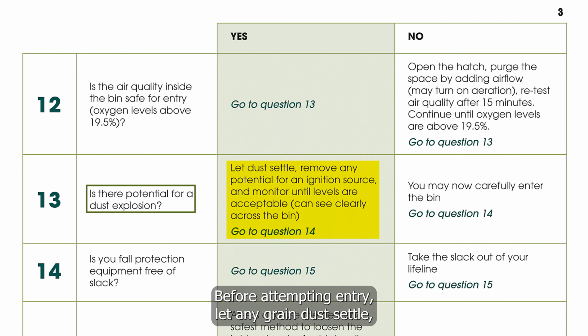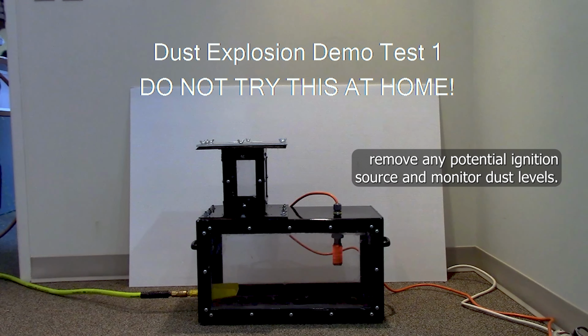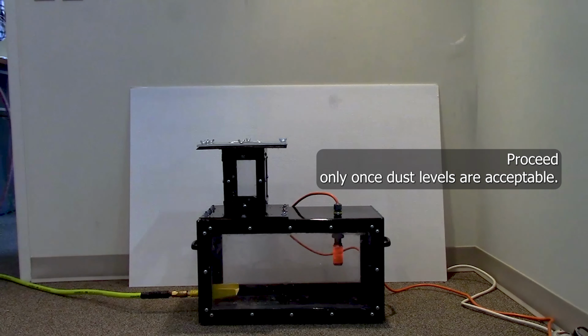Grain dust is highly explosive. Before attempting entry, let any grain dust settle. Remove any potential ignition source and monitor dust levels. Proceed only once dust levels are acceptable.